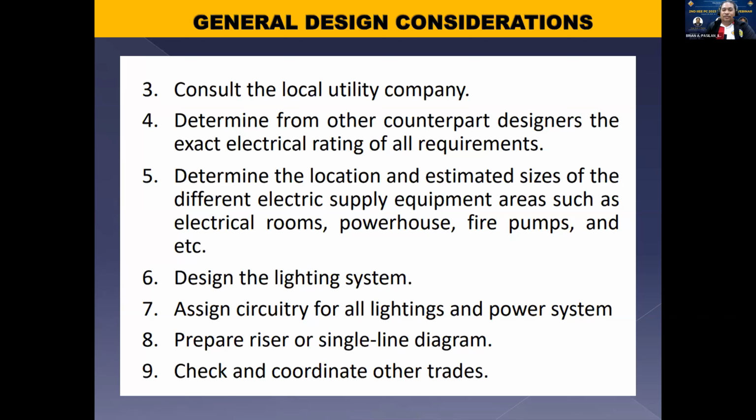which of these will yield a higher demand. If the low density method gives a higher demand, then let's use that power requirement. The ratings from the other designers, we can use in the load assignment, in the circuiting, for the specific outlet with its rating. But for the feeders, the main feeders, we have to use whichever is the higher value: the load density calculation or the actual load given by the other designers.